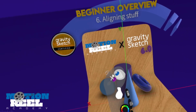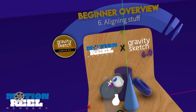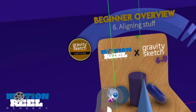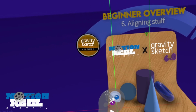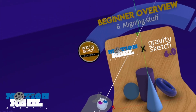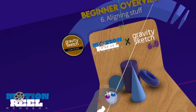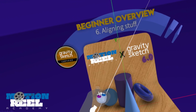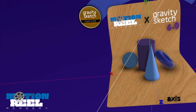And if I half pull my non-drawing hand trigger, like so, you will see there is a line that pops up. This is the alignment line. If it is on an axis, then it will be colored. If it's not on an axis like this, then it will not be colored. You can align a shape or set of shapes to this line if I wanted to draw out. So let me show you how that works.